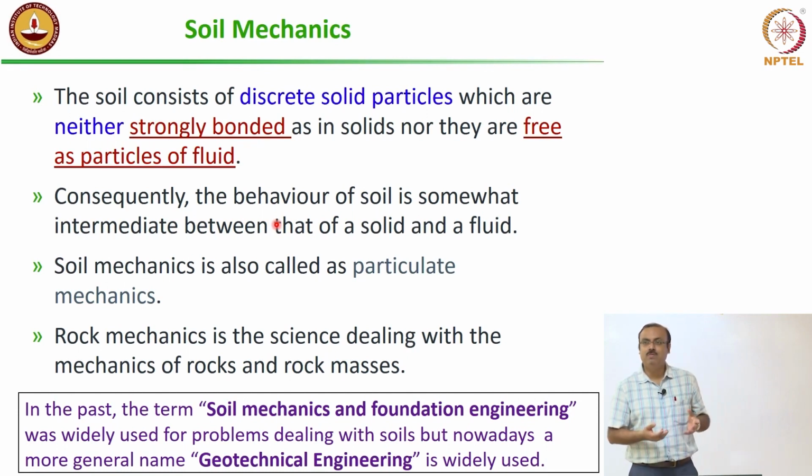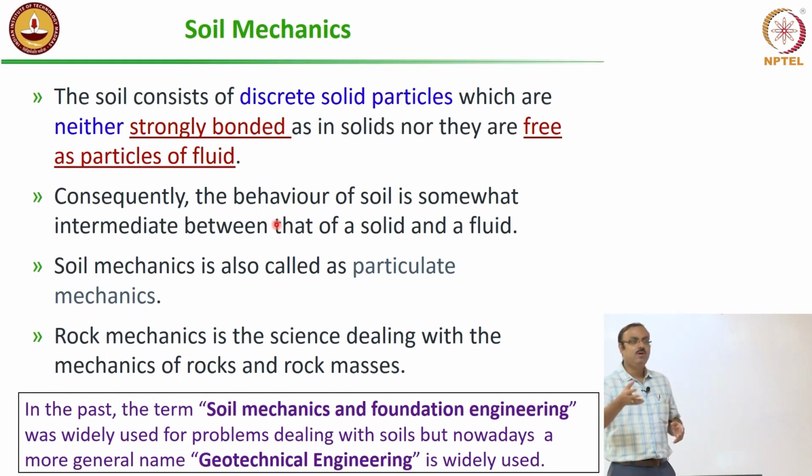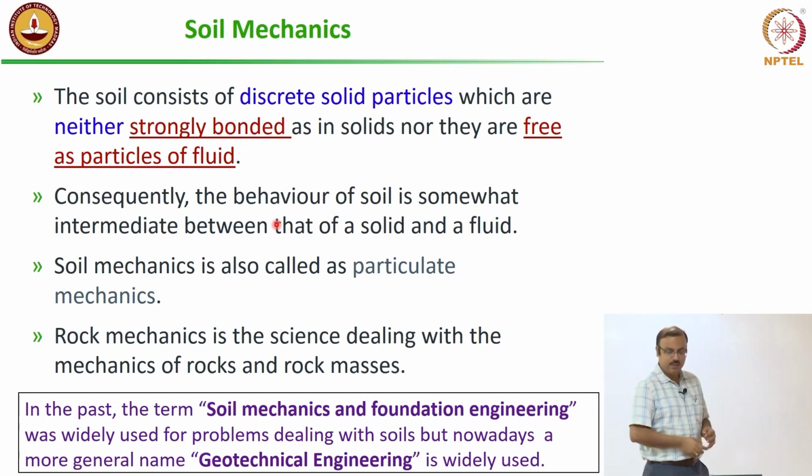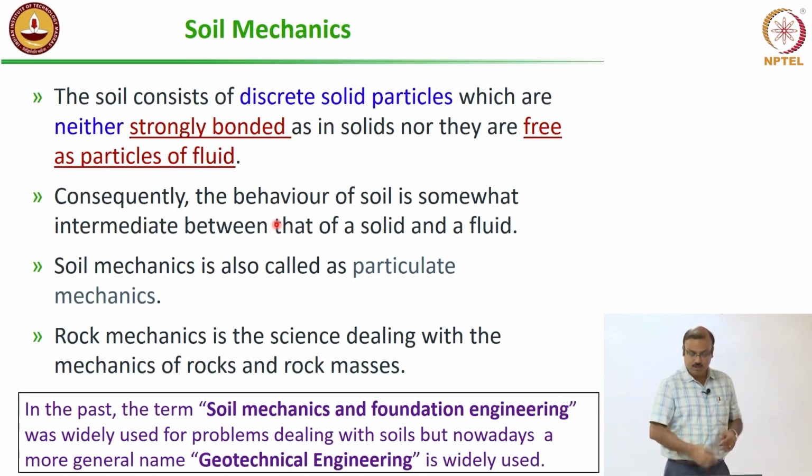So, always in soil mechanics, a foundation engineer or civil geotechnical engineer deals with a situation where three different phases are always present: solid, liquid and gaseous. Any time you take a sample of soil, you will have the water, you will have the soil particles, that means the solid phase, and you will have the gaseous phase. So, that is the big challenge. That is why some people want to call it particulate mechanics.